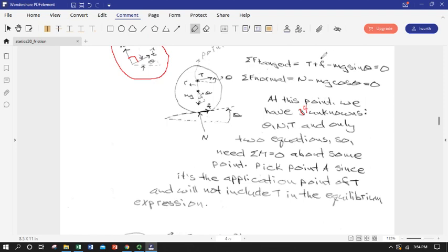So we're going to have to invoke an imminent slip to replace F. I was getting ahead of myself when I wrote 3 equations. I was already envisioning putting this in the imminent slip criteria, and because I'd already planned to replace F with a term that included N. But even if I did that, I've still got 3 variables and only 2 equations. So I'm going to have to invoke a moment equation to give me another one to be statically determinate and then express theta in terms of everything else.